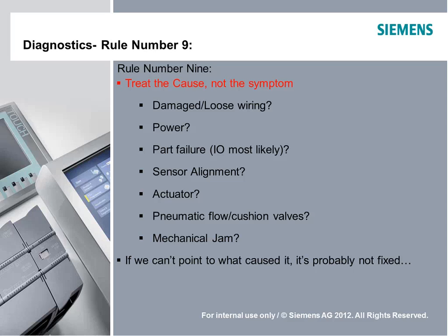Sometimes it's just that the push arm can't return all the way back because it's got a bunch of cardboard box pieces behind it or something, and that's typical of machinery. One of the things to think about with a machine, especially one that's been in the field for a long period of time, is that typically software doesn't change. So it may have a PLC in it, it may have a very complex program. But if it's been working for a long length of time, chances are pretty good you don't need to change the software. These electrical wiring issues, the mechanical jam issues, the cushion valves and sensors, and all those things are much more likely to be causing a problem.